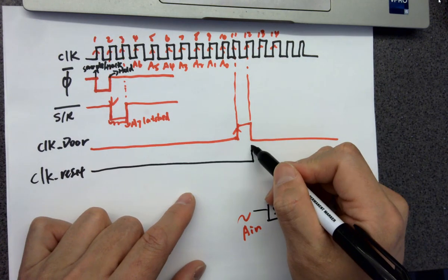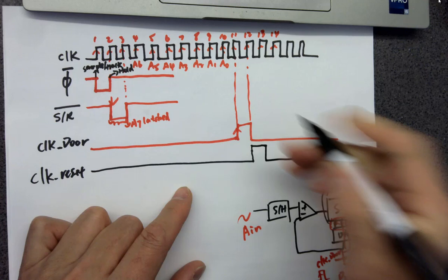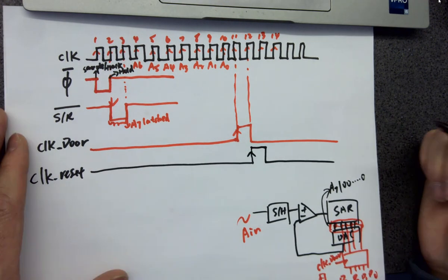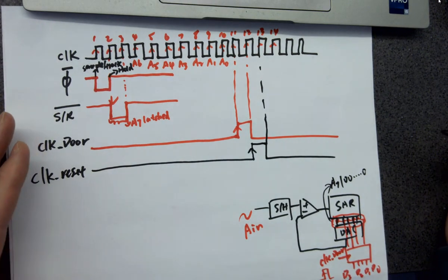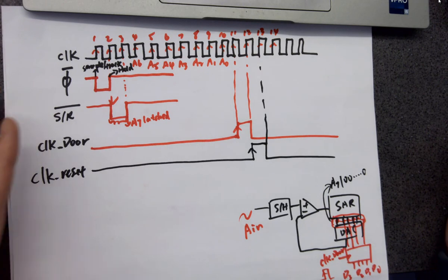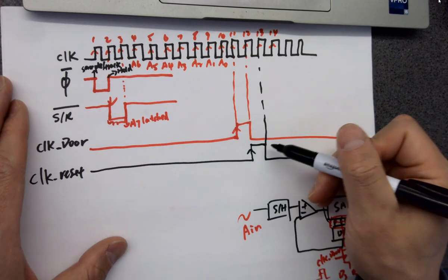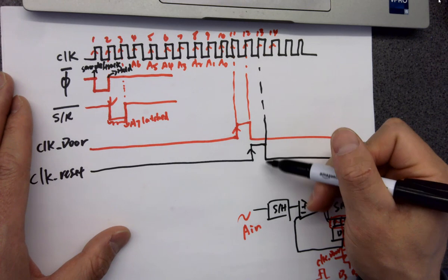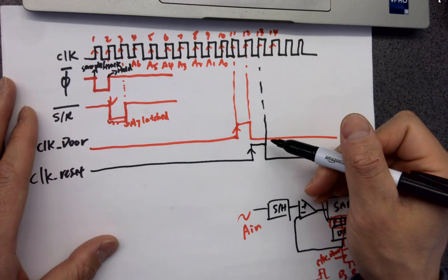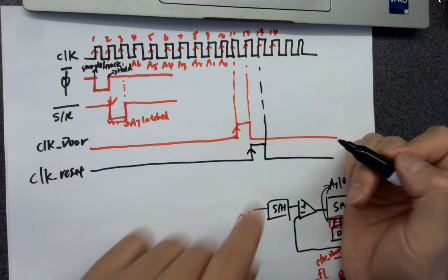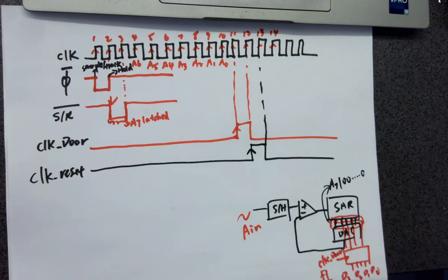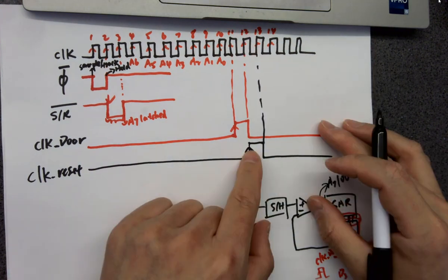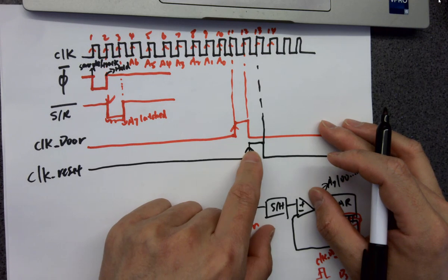So you want to reset it. We need a reset signal for the counter. This guy, reset it. At the falling edge of the reset, what can I do? Because here, at the rising edge, the counter will be reset to 0. The counter starts counting from zero, and after this point, the counter is already reset.